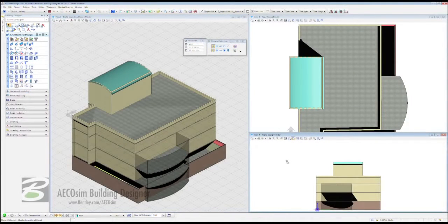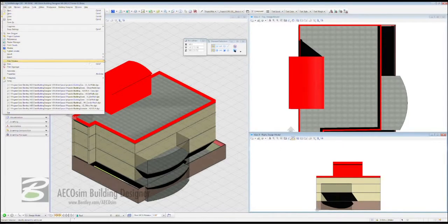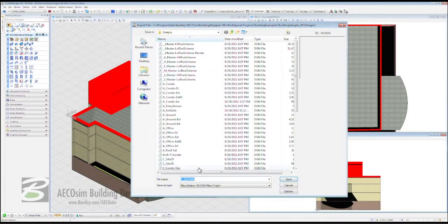So now that we have all of our elements together for this session, we need to export one more drawing out. We're going to come down to our elevation here, have a selection set from right to left, highlight everything that we've placed down, our parapet walls, our curved roof surface, and the walls that came up to meet them. Come up to File, Export, DGN.